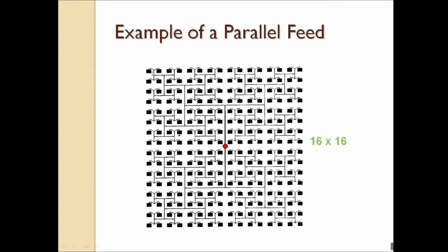Right now you take these 4 antennas, and the lower one, the next lower 4 antennas. All are connected with the help of another feed. Right? It is a feeding line that will supply these inset feeds. Similarly, it will extend to the center point. You see, from the center point, the lengthier feed will split into 4, then each 4 again split into 4. Like that, it goes on. This is nothing but a parallel fed antenna. It's an example of a two-dimensional array.